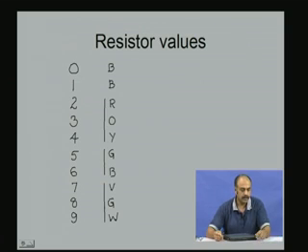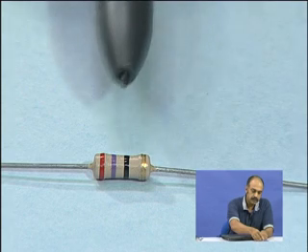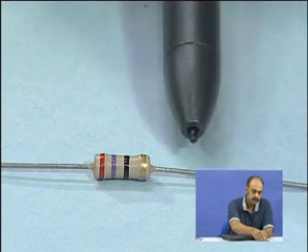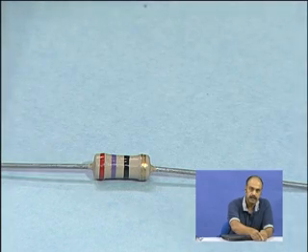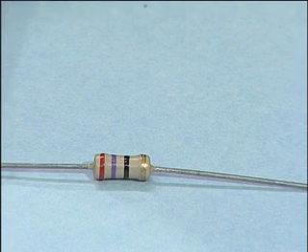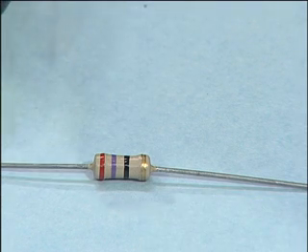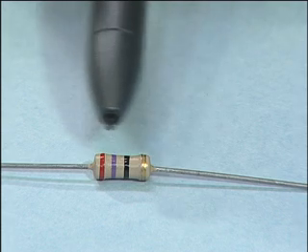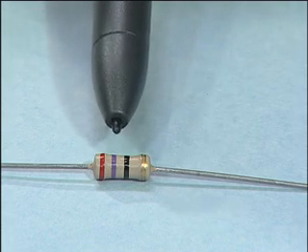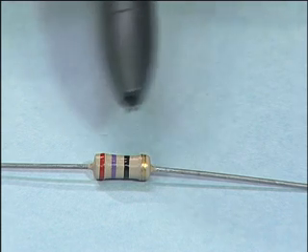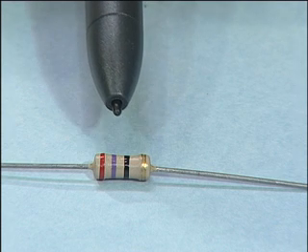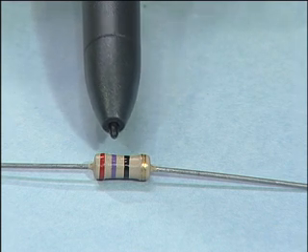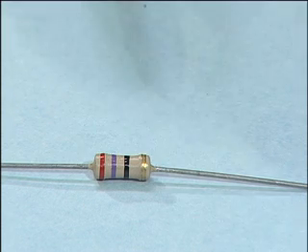What you see here is a resistor which has two leads. There is one lead here, there is another lead here, which gets connected to your circuit, and this portion is the resistive portion which impedes the flow of the current, and there is going to be loss, the I square R loss or the V square by R loss or V into I loss, any one of those equations.